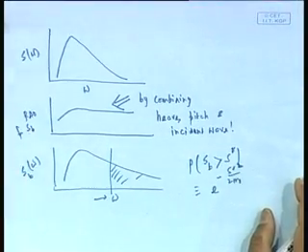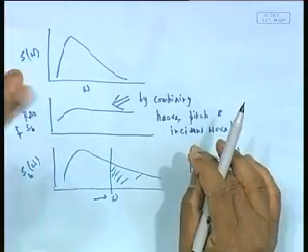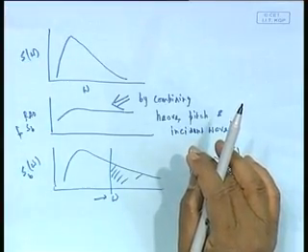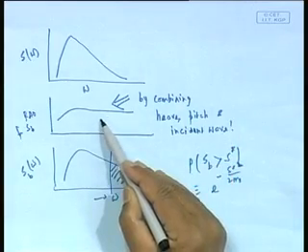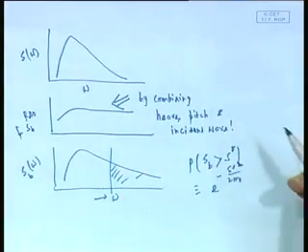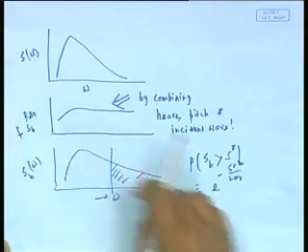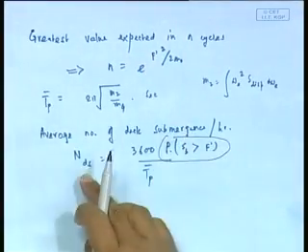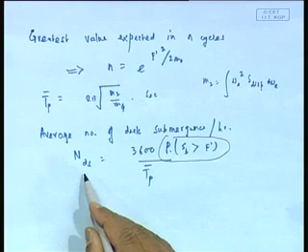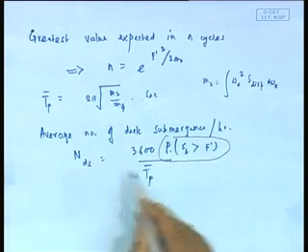So, the procedure becomes very simple. I do a calculation, I have all the 6 modes of motion. Now, I want to do my loop 1, what is the deck green water shipping probability. So, I will first of all find out this RAO. I know my freeboard, the modified freeboard f dash. So, I first find out this RAO, in one particular line I find the area under it, m0, and in the next line I simply come back to those relations, and therefore I output the number of times the deck is expected to get submerged per hour.